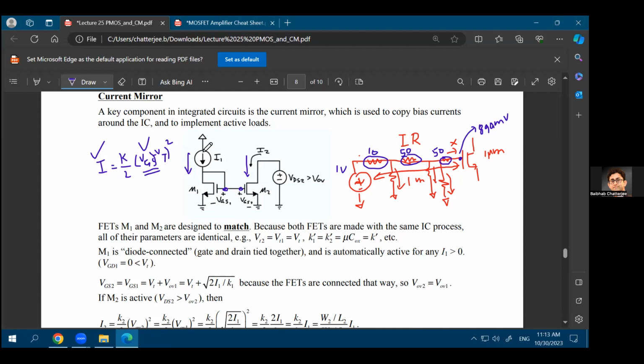And if you're creating this voltage with a current, according to KCL, that same amount of current has to flow through the drain as well as the source of this transistor. And if the current does not have much noise, then the voltage that will be created at the gate of the transistor will also not have much noise. So you can also create a very good current source externally and feed that current so that the effect of noise is less when you're biasing the transistor, and also the effect of IR drop is not present at all, because now you do not have these resistances in the path. Or even if you have resistances in the path, let's say this current source is provided from the external world, there are resistances in the path, but those resistances do not matter. There would be IR drop across those resistances, but what you are concerned about is just the current flowing through the transistor. You do not even care about the voltages anymore. So that's the advantage of biasing using current sources.